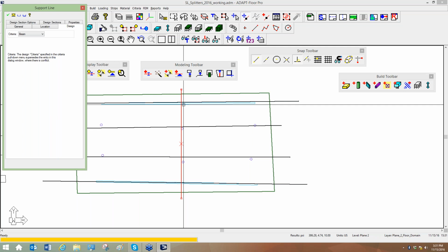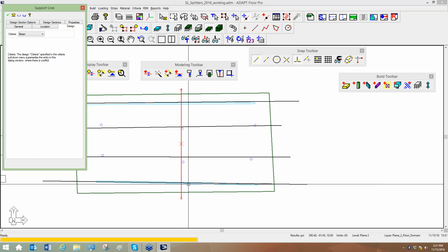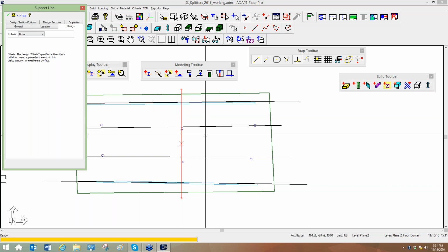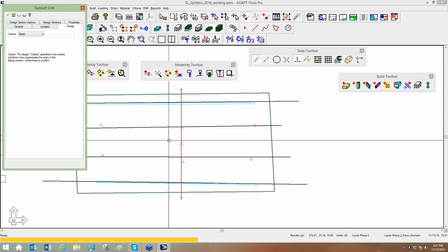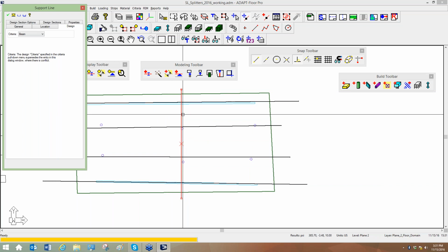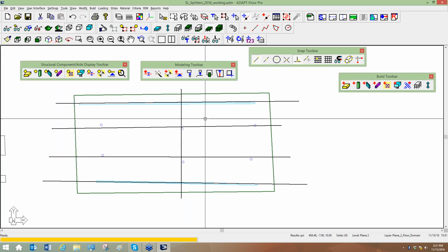If you go to that extent in dissecting the design, then you could run the model with one-way strips to get the rebar in this end bay, and go back and change them to two-way to get the rebar in the middle portion of the slab. Or you would discontinue the support line, let's say at the mid panel, and then create a one-way strip.